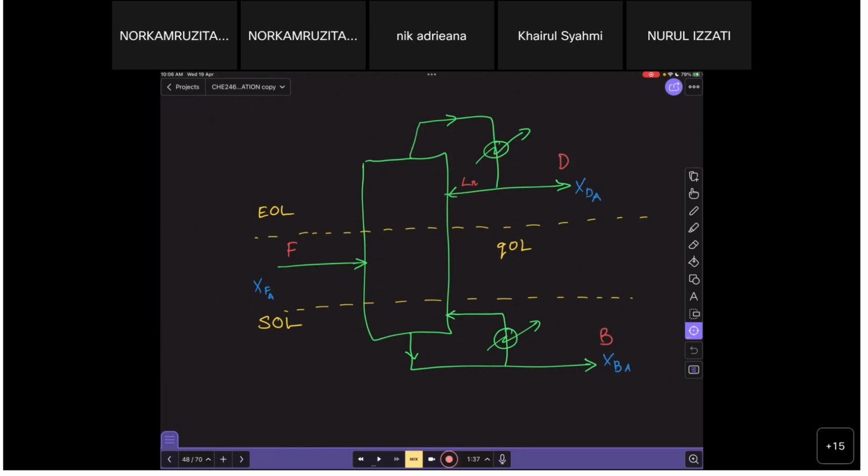The reason is very simple: to increase the contact between the vapor and the liquid again and again until you get a very purified component A at the top of the column, where you collect it at D. The reflux ratio formula uses Ln and D, so R is equal to Ln over D. That is the information you use in the enriching operating line.